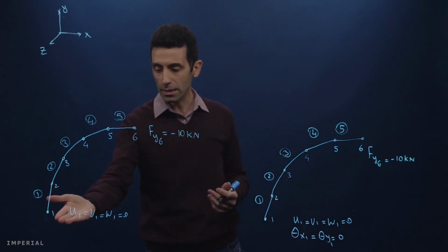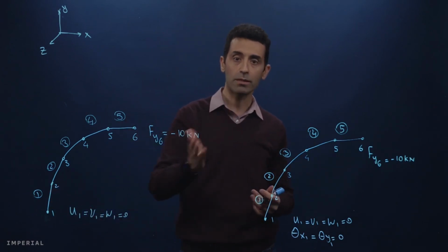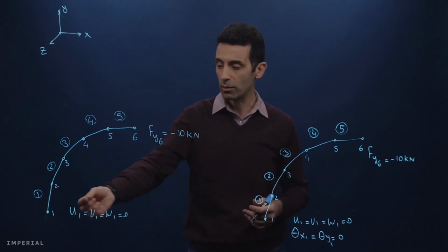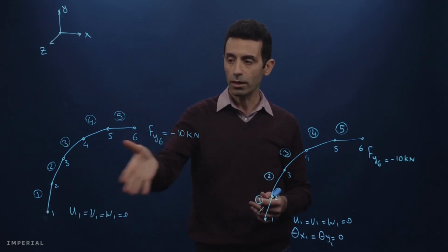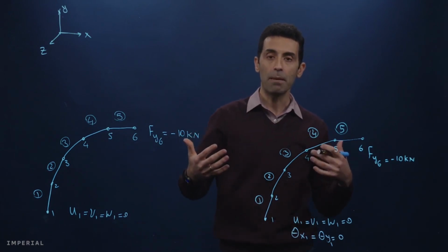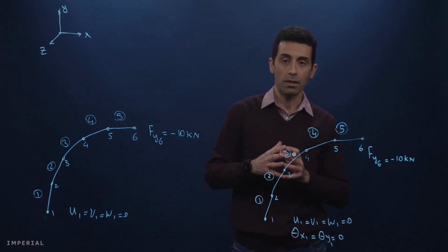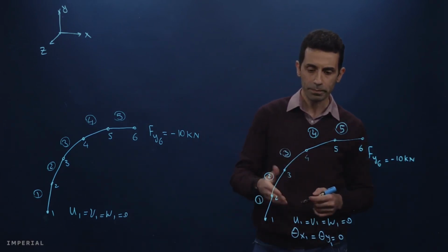Here you can see that we are fixing the translational degrees of freedom, but rotational degrees of freedom are not fixed, they are free. Essentially, we have a hinge at this point. So when this force is applied, this whole structure starts rotating. So it becomes a mechanism, something dynamic, and therefore the mathematics will fail, right? So then you will have the error.